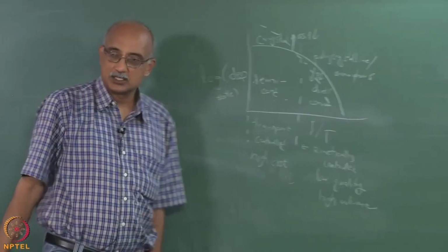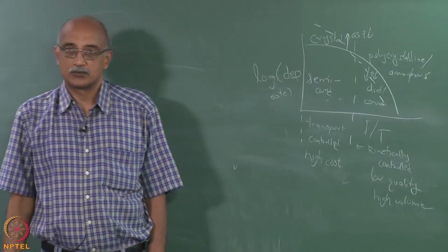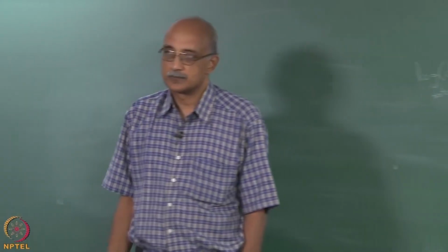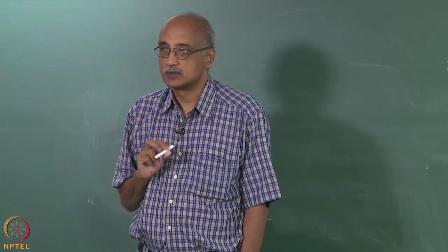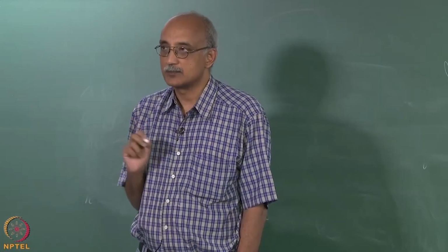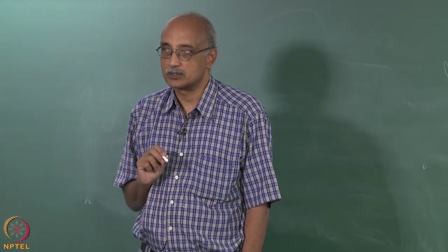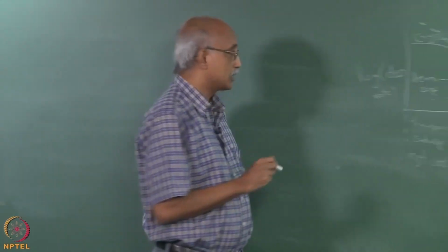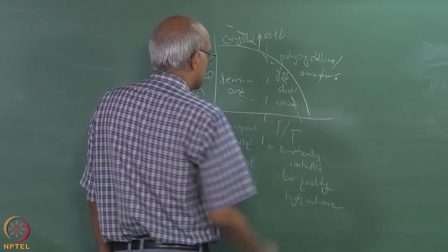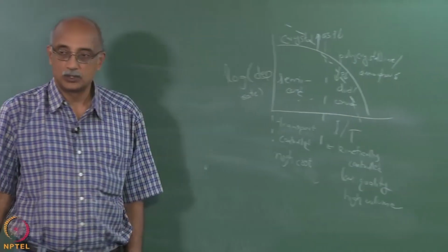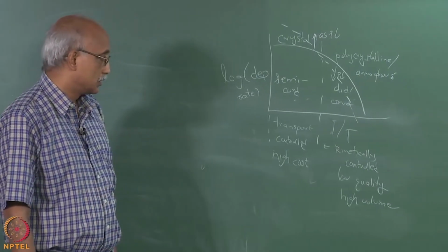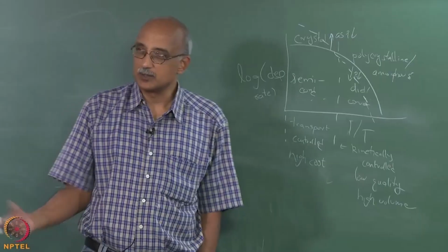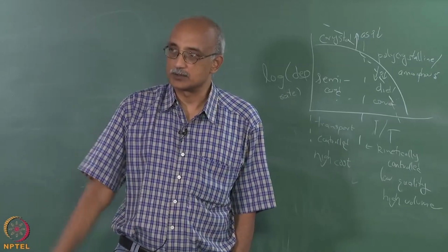Will the dew point change in this case if you are playing around with the pressure? The dew point is a thermodynamic parameter. So, yes, pressure and temperature will play a role on the dew point. So, yes, it will change, and most likely the dew point will move to a higher temperature. What does that mean? Makes it more difficult to deposit, right?